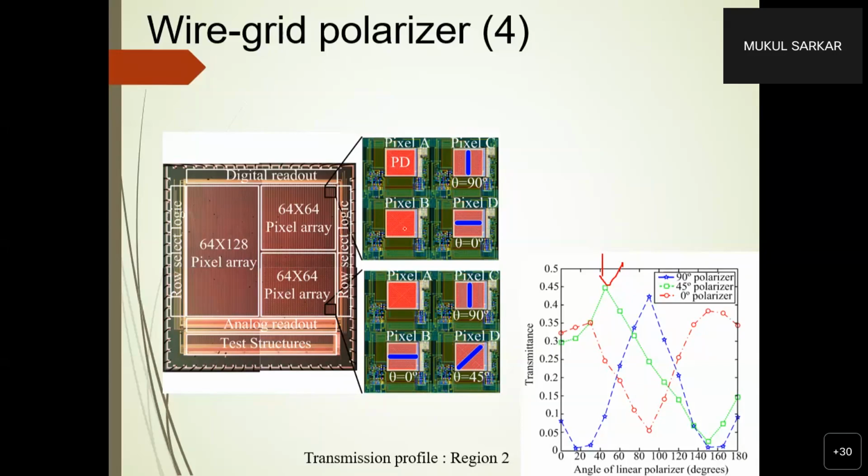The processing power is substantially high, and that causes the HDR camera to be very high power. Now, if you have very high sensitivity in the pixel itself, then you don't have to do a lot of FPGA processing. And if you don't need FPGA processing, then the power consumption is not going to be substantially higher. It's going to be considerably lower.